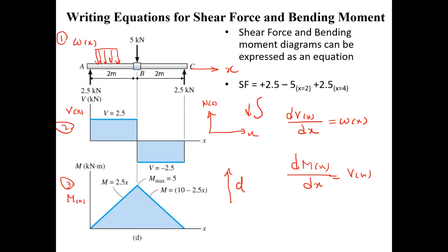All right, so we went through a good number of examples last week, and we keep doing the same thing now. In that sense, what happens if I do have point load rather than W of X? If I do have point load, who can tell me what is the difference? Point load could be either a shear force or a point bending moment. The bending moment is regarded as point rotation. This is a point load, this is a distributed load.